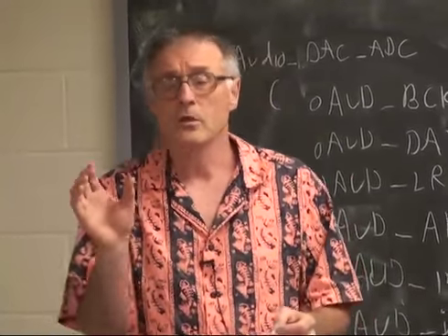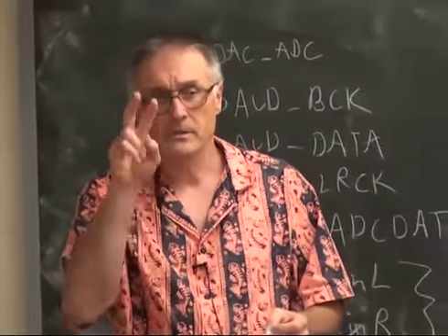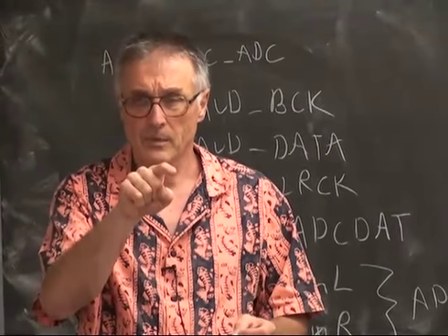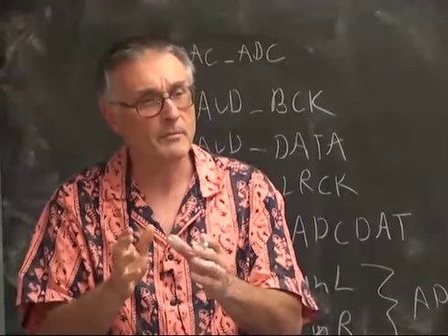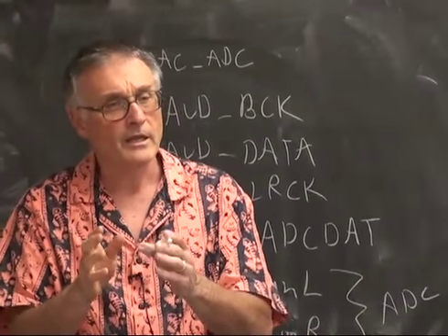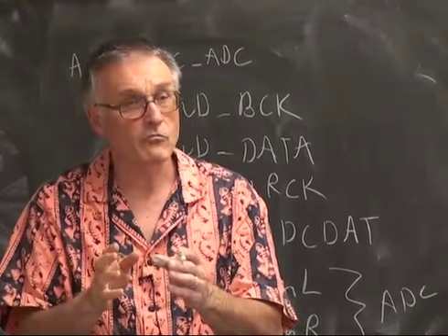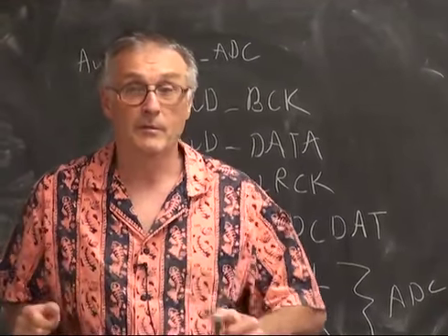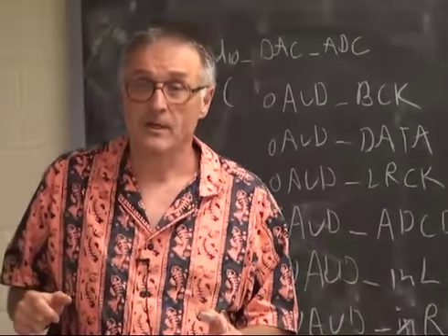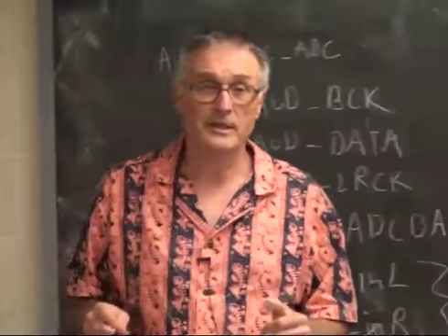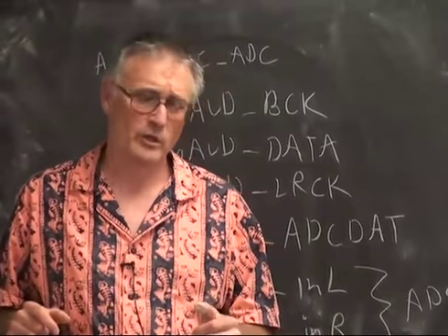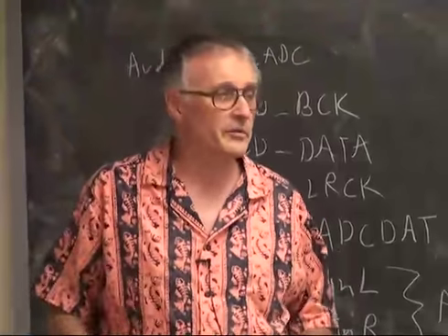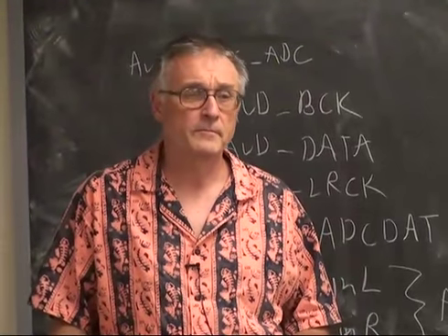Okay. To the left of that panel is a menu. If you click on the timing menu item, it'll pop open a submenu, and if any of those submenu items are red, you're in trouble. That means you have a timing violation. That means you tried to get a signal through the chip in a negative time. It's not good. So, said differently, you need a negative delay someplace.